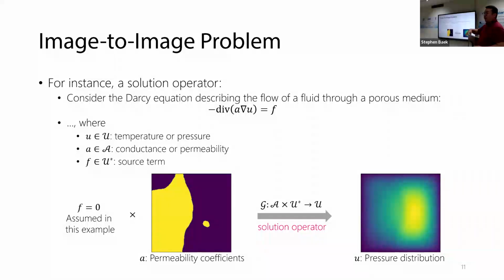When you have, say, a compound of stones, sand, and various different materials on the ground, and you pour water, then depending on the composition of the rocks and sand, the water will flow eventually, but the rate of flow is going to change, right? The Darcy equation is basically the equation describing how that fluid flows inside of those porous media, and it looks like this.